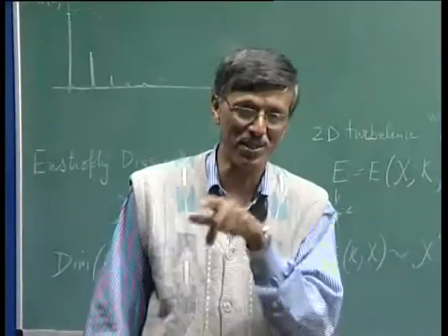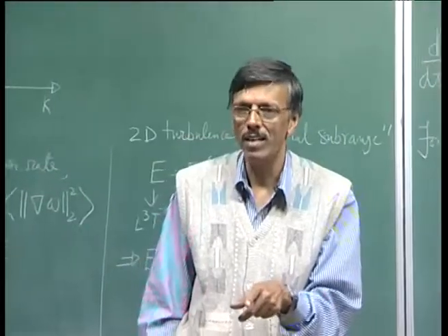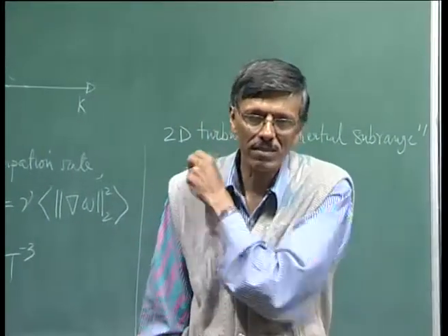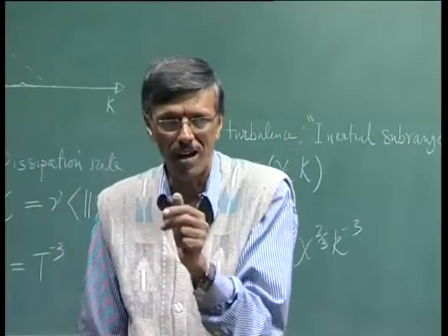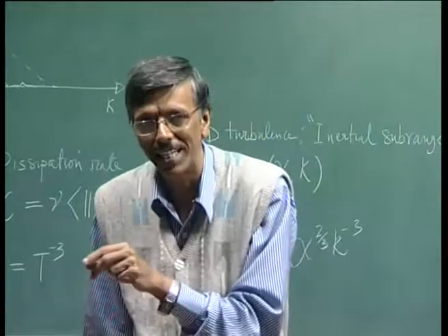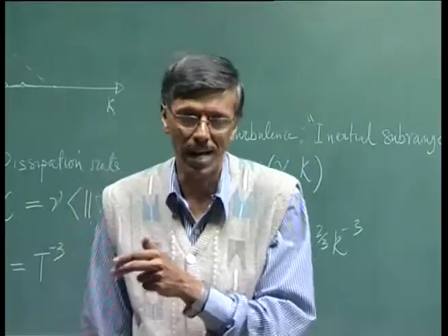Sir, we discussed the Kolmogorov scale. So, when we do computing, these scales are affected by computing. The scales of course are not affected by computing, but your computing should be able to resolve those scales. That is the point we made, that the Kolmogorov scale is the smallest scale that is excited in a flow. Beyond that, everything is dissipated into heat. So, you cannot have eddies smaller than that size, or fluid flow entities retaining their identity and having kinetic energy beyond that scale. That is what you want in direct numerical simulation.